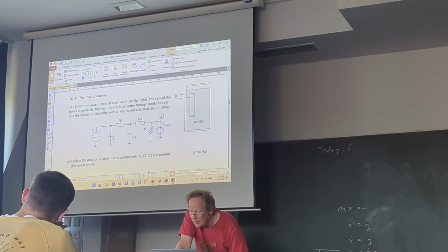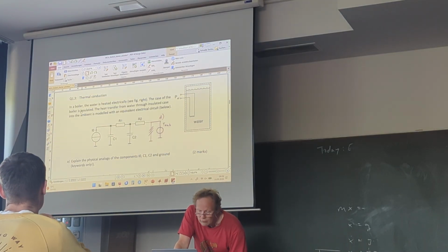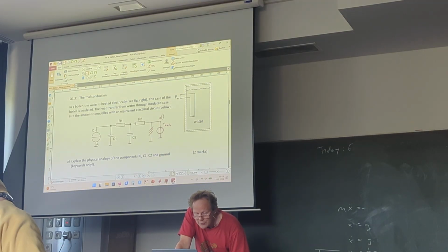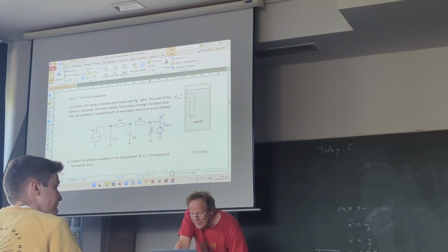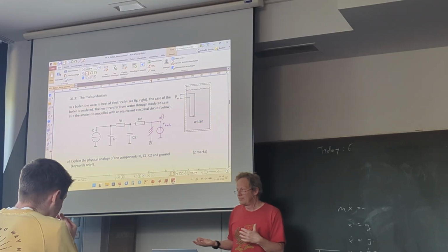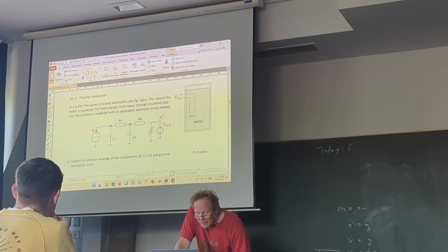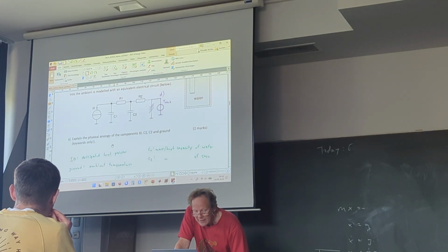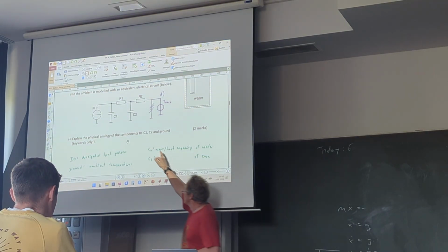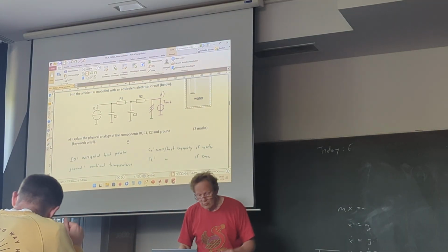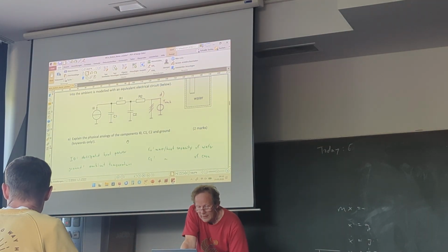So we have a stream of power, which can be modeled as a current source, so heat power. And we have 2 resistors, and then we are here initially at ground, that means in the ambient. But we have more, we have 2 capacitors, and now we should explain the meaning of these capacitors, but also that of I0. Ground was already set, corresponds to ambient temperature.